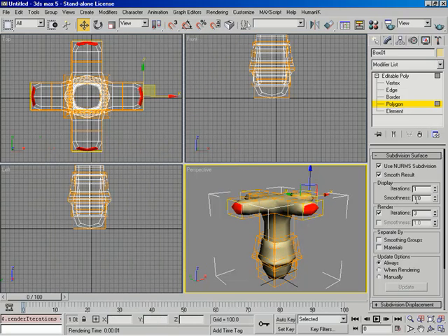All right, what smoothness will do basically is the subdivision surface, or NURMS, is going to look at all of the corners, where all these edges come together. And it's going to look at the actual angle. Then based on the setting that we apply for smoothness, it's going to determine if additional polygons need to be added in to smooth it out. So watch what happens right now if I start taking my smoothness down.